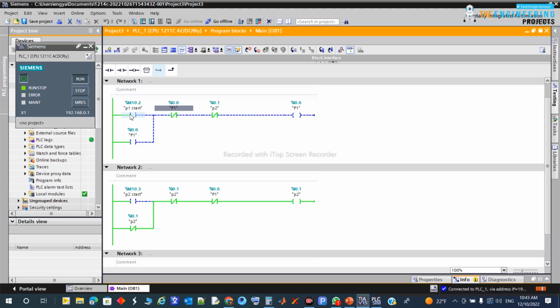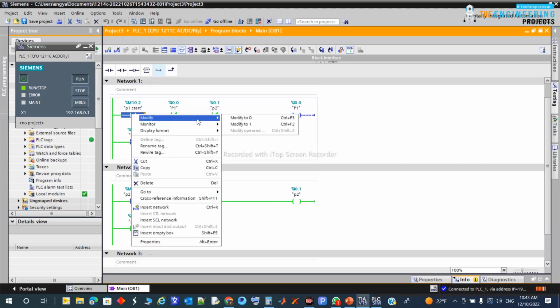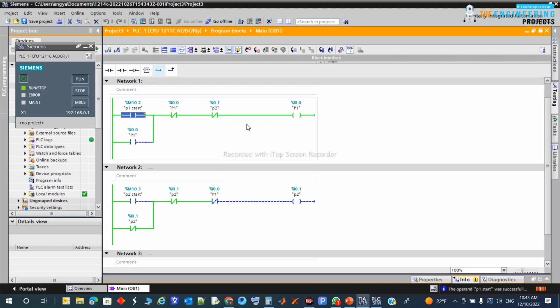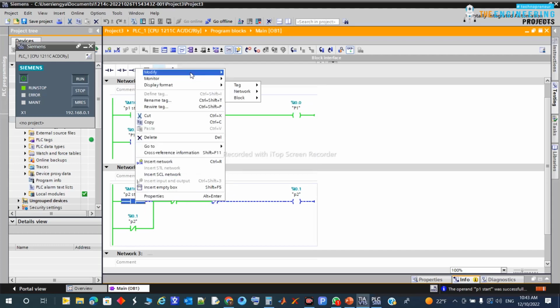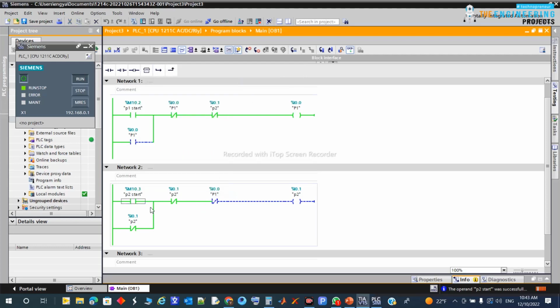So let's try to start the other one while this one is running. Let's start running this one and see what happens. Once I requested one of them, the other one can't work, because I just opened this bus from B1. And same thing here, if I start the other pump, what's going on? Yes, for sure, if I start this one to open, it can't open. Why? Because this one is already open. It tells me B1 is running, so you can't run both of them.